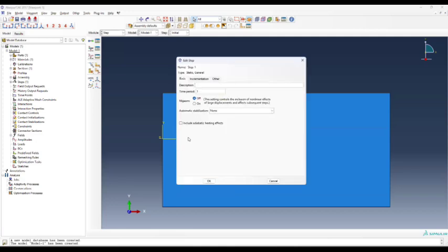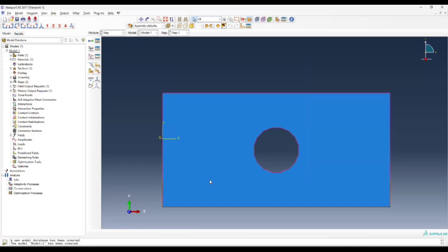But just keep in mind this nonlinear geometry: if you have very complicated loading or very complicated geometries, you would turn that on such that the CAE can adjust for that. But for us, it's a very simple problem. We don't need to turn that on. You don't need to worry about that either. This is for incrementation, so if we want to more finely track our simulation, we could do that. But all we need to do is hit OK here. We've created our step. Okay. So any questions so far?